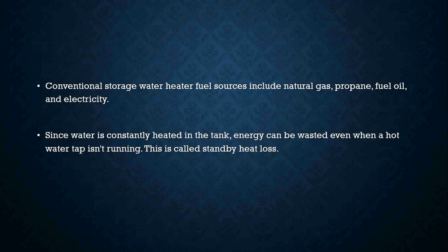Now think about where most of your water heaters are located. Probably in a home, they're going to be in a basement. Most likely, probably right next to the boiler, especially if it's an indirect. If that water heater and those hot water pipes are in an environment of 40, 50 degrees, we know from the laws of thermodynamics that heat will always go from hot to cold.